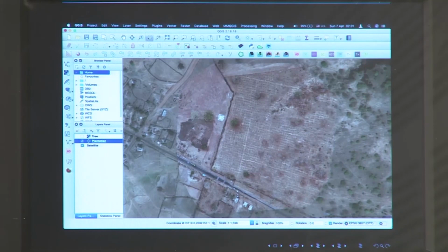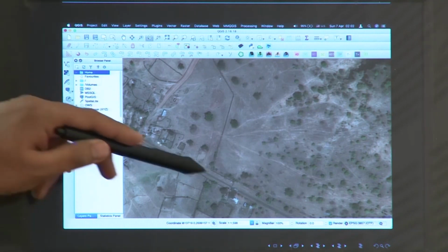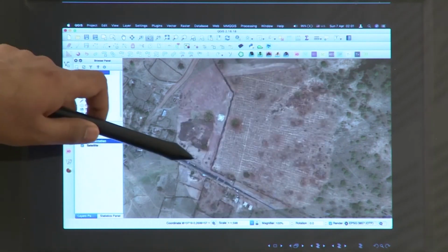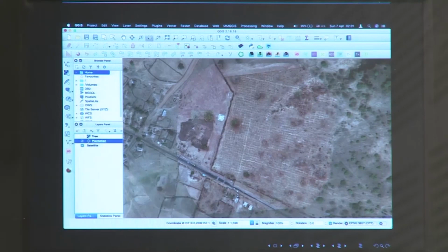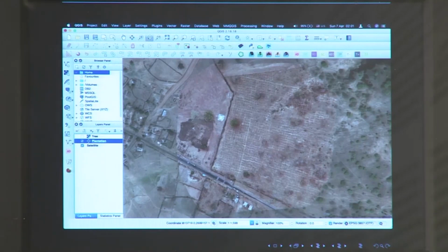So, we are using the technique of photogrammetry to interpret the whole situation. We can see where we had a construction, where we had a plantation, where there was an excavation, and we can even see what was the difference in the road. In the previous image you have a plain road, and now in this image you can see that here the road has thickened and here it is a single lane road. So, probably this road was expanded after the satellite image was taken. So, now you are using photogrammetry to interpret different locations to get an idea of your area.